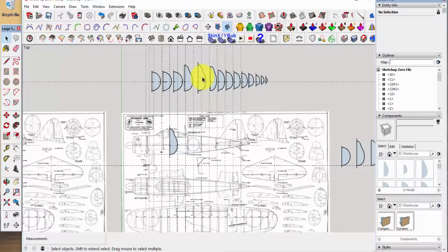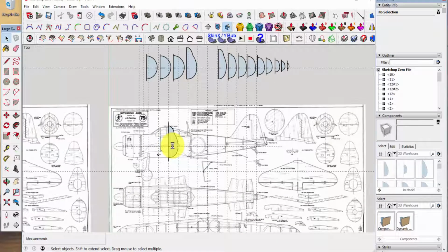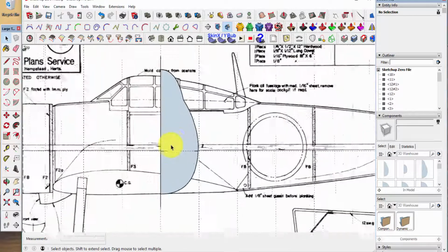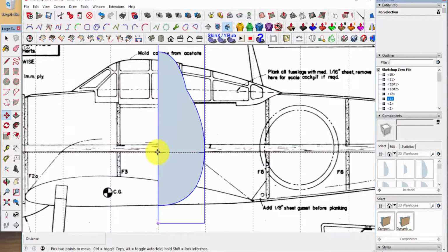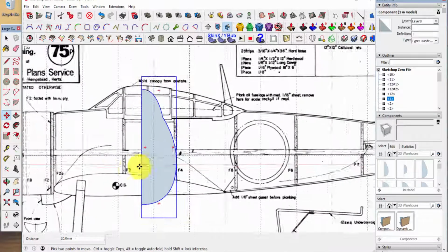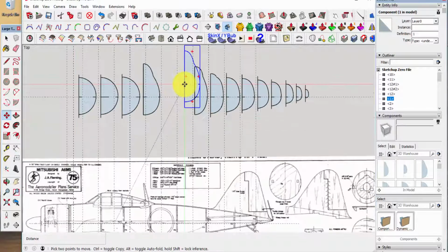All right, now we've gotten the second one done. So this one we'll do away with. We'll come down here, auto saving again. Select M for move, grab it on our reference line, and pull it back up here.